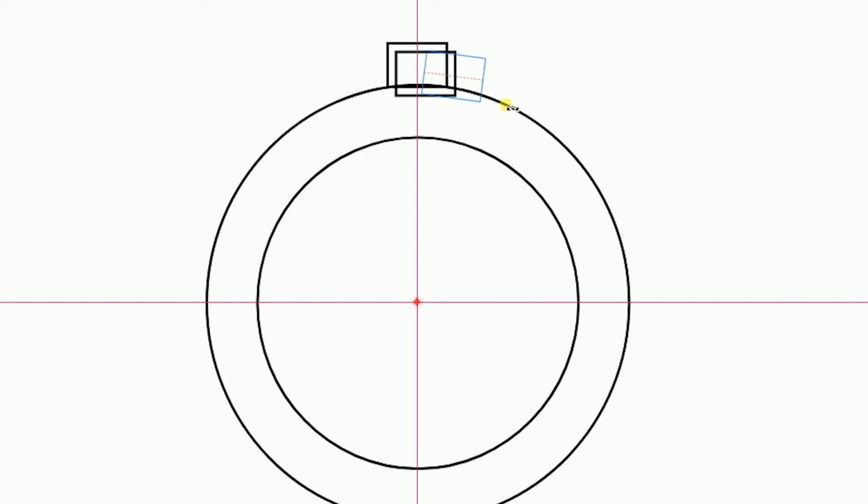Now you see you can rotate your bounding box according to the point of your transformation. What's more important, guys, if you hold Shift, you can constrain the angle of your rotation to 15 degrees. So everything that applies to the simple transformation also applies to this smart transformation. So if you want, you can set 45 degrees. And then what's more important, you can then repeat this transformation.